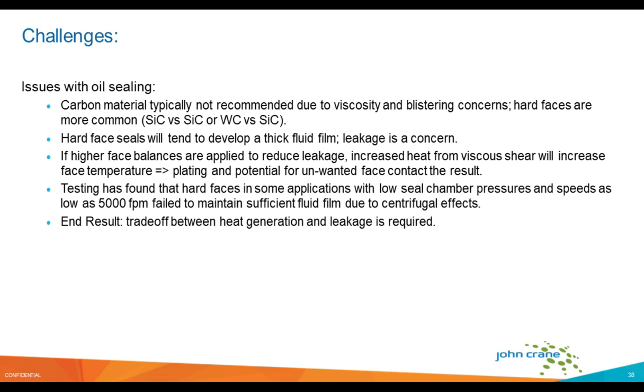If we try to minimize leakage by, say, increasing hydrodynamic face balance, we can possibly reduce leakage, but the trade-off is that we create more heat, because now we're pushing that oil. We're creating increased heat from shearing of that oil, increased face temperatures. We may get some plating and unwanted face contact. So face contact, in this case, at 13,000 RPM would not be an ideal situation.